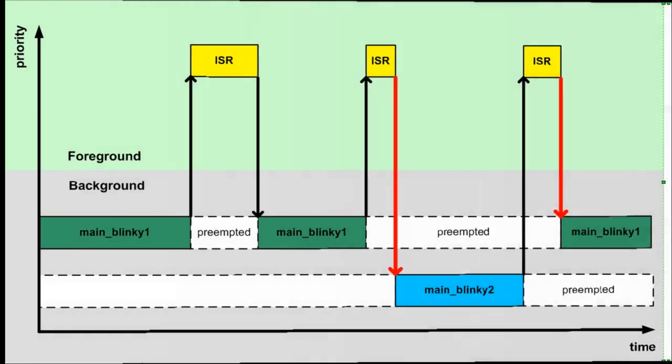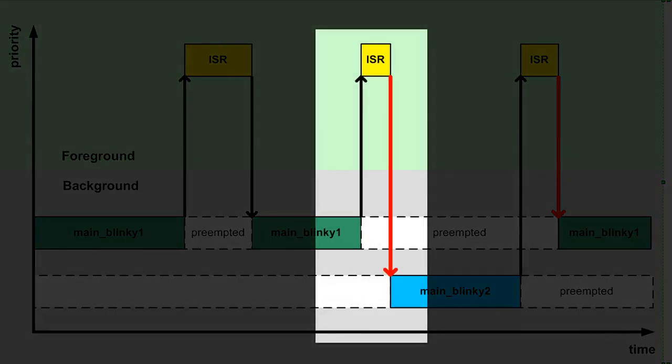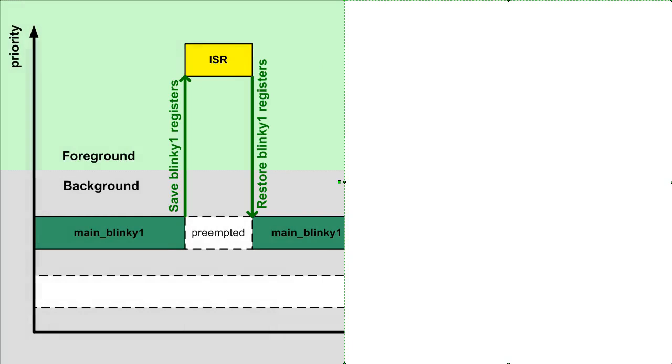Now, in the remaining part of this lesson, let me go back and explain why changing the PC register value on the stack was illegal and what you really need to do to switch context cleanly from one thread to another. To illustrate the problem, let me use colors for the registers that are saved and restored by an interrupt.